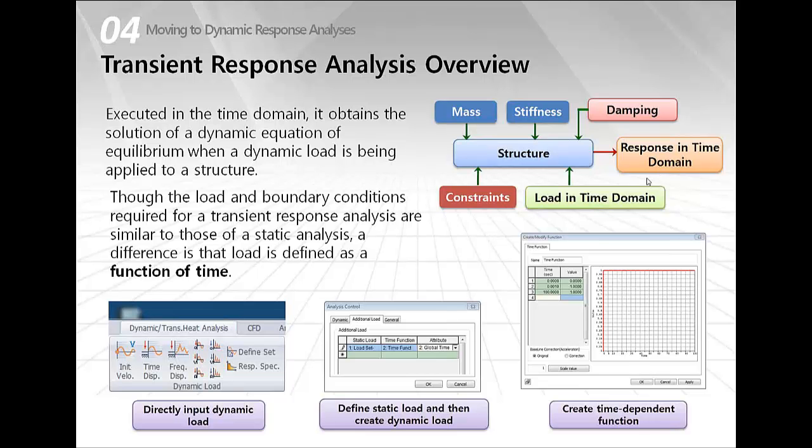So in Midas NFX, analyzed structures can be subjected to nodal loads like velocities, displacements, and accelerations, and we can apply them directly on the structure with reference to the time function. But there is also another way to apply dynamic load.